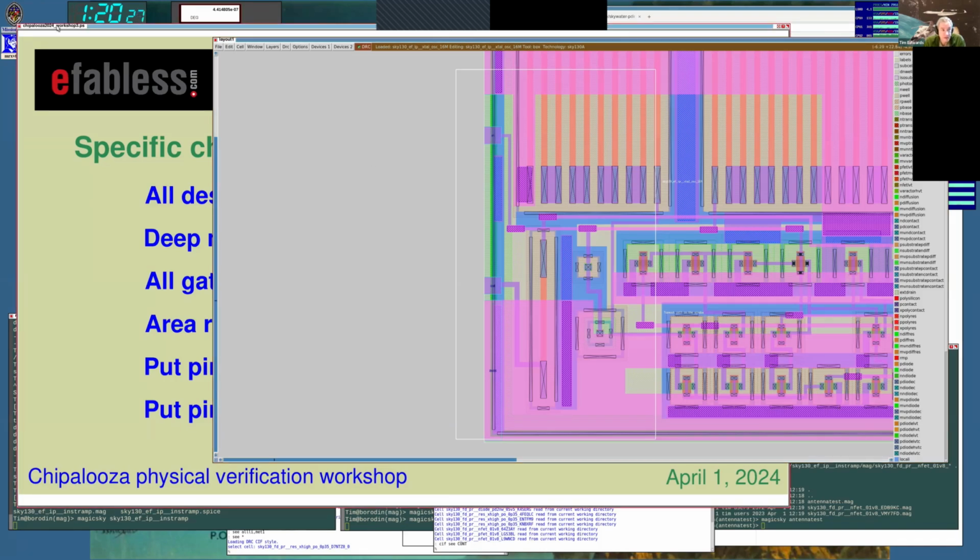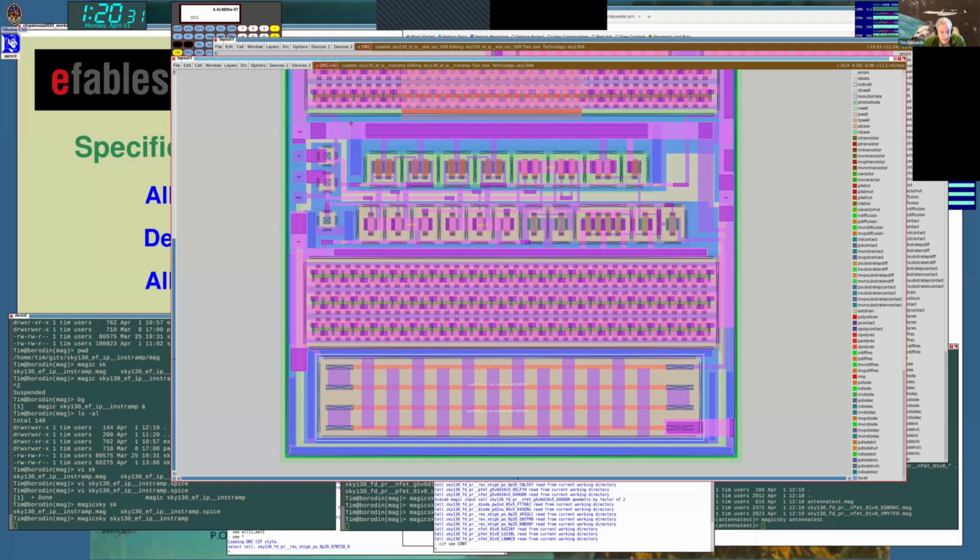In the other layout, which I had back here, I use diodes for a different reason, and these are inputs that are being routed internally. So this is the negative and positive inputs of my amp. I'm connecting them to diodes just so that it will resolve antenna violations. That way it's much less likely that routing this out to some other circuit is going to end up being an antenna violation. When I get to the DRC section, I'll go briefly through antenna violations, if you don't know what they are and what you're supposed to do about them.